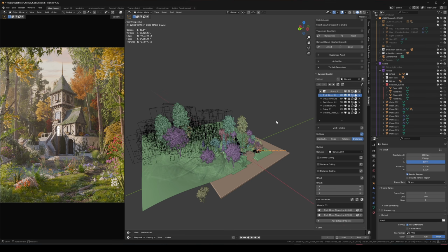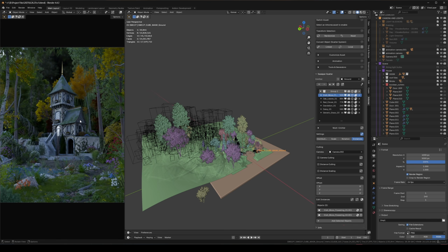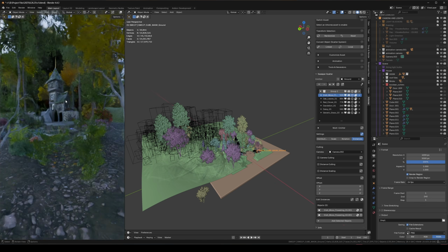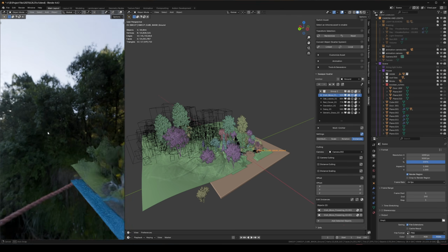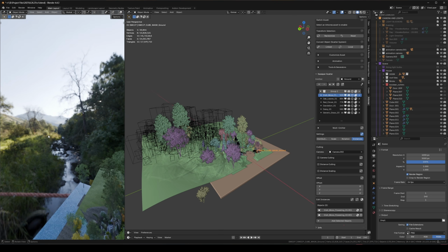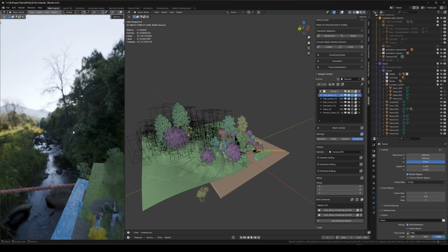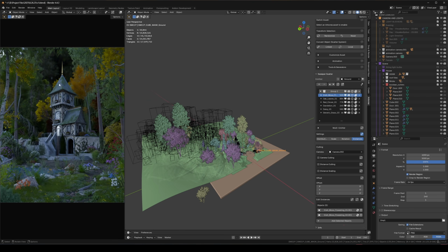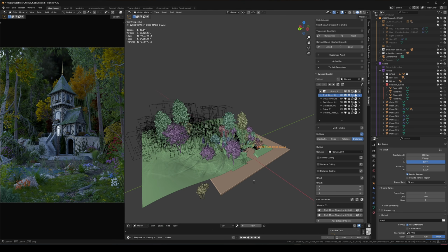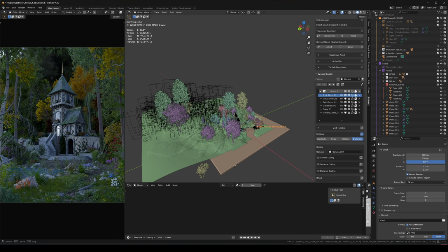If I turn off the lighting, you're going to see just the scene with only the HDRI. The HDRI that I'm using doesn't really have that much direct lighting. It's mostly just for the ambient lighting. You get a little bit of a cool highlight on the left side, but it's nothing too strong. Most of my lighting is coming from this sunlight right here and the sky in the background. So let's start with the HDRI because we already have this right here. This is just a really basic setup.